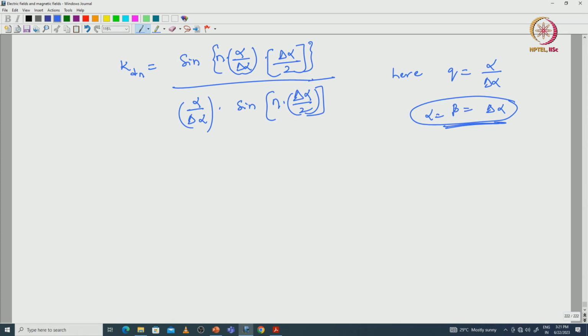Here, in order to find the behavior of this function where delta alpha tends to 0, delta alpha is nothing but the angle between two small straight bars. If delta alpha tends to 0, what is the behavior of this skewing factor? We have to analyze. For that we have to apply the limits with respect to the skewing factor, Ksq, I am representing that one.